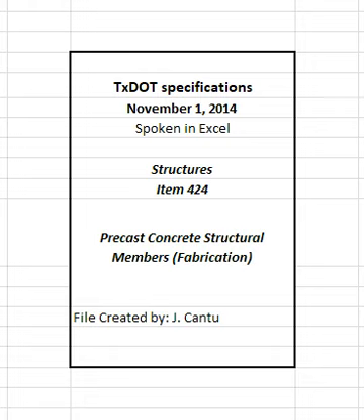Recalibrate jacks and gauges when a malfunction occurs, when repairs such as replacing the seals, changing the length of the hydraulic lines, or changing the pump occur, or when using gauges that have not been calibrated with the jack. Extra compensation will not be allowed for the initial or subsequent calibrations. Post-tensioning jacks must have provisions for measuring tendon elongation directly on the strand, bar, or wire. The jacks must be capable of slow release of force to properly seat the tendon anchors.